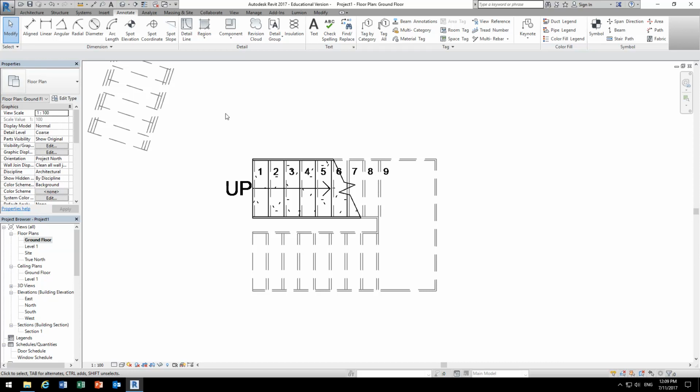Sometimes you can't just copy and paste. Certain things aren't selectable in that way. So there is another way, and that is to paste it directly into the family section in your project browser. That works as well. So you can go here, right click, and it's not there because I haven't got the right option, but you've got the option to paste there in some cases.